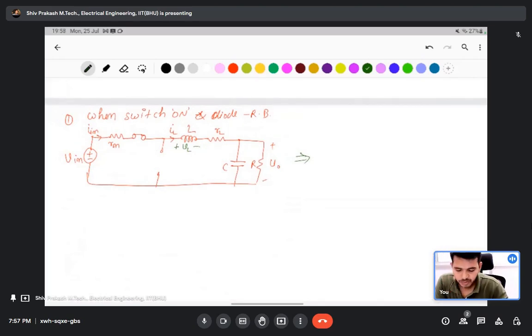First, in this circuit, to find the output voltage of any converter, you should know about the voltage balance equation and the current second balance equation. Because of any inductor circuit, if you take an inductor, it should charge and discharge within the period. If it only gets charged and never discharges, then the inductor gets saturated and the circuit will not be completed. The same thing occurs in a capacitor.